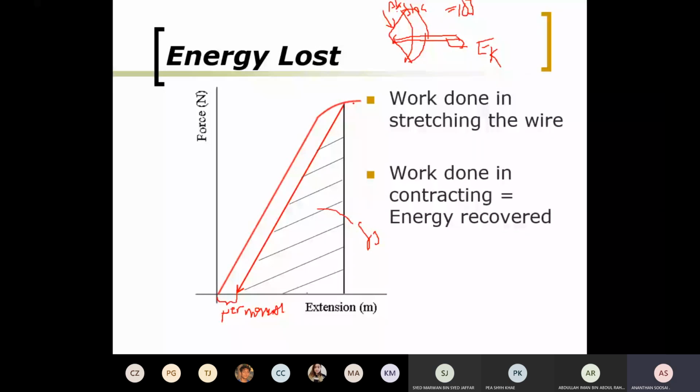So if you reach plastic deformation, the energy you stored is greater than the energy recovered. In the exam, they'll ask you to shade the region which is energy recovered. So the area under the graph of the second line is energy recovered. The area bordering the two lines is called energy... I won't say lost. Please remove the word lost, because it has a permanent deformation.